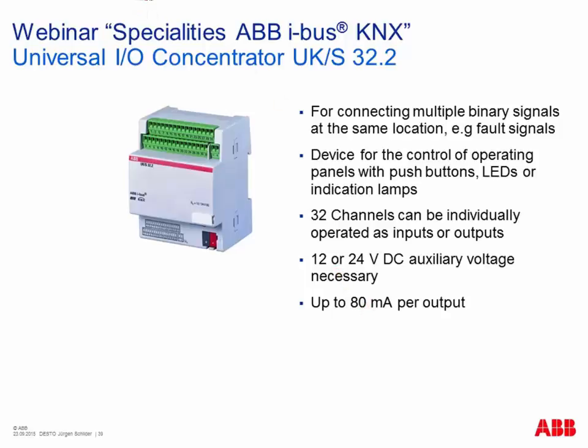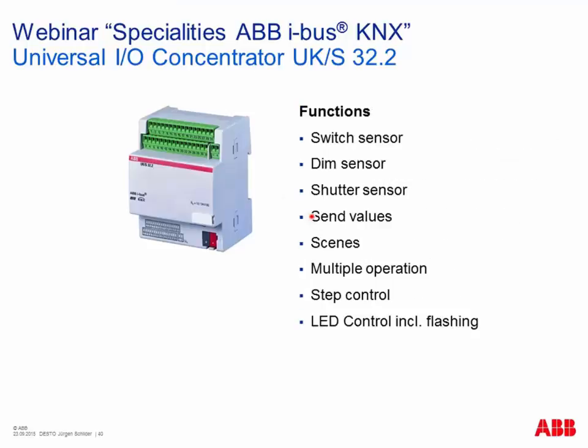And the input function mainly used is comparable with classical binary input, with all these functions from switching up to dimming, creating light scenes, and also multiple operation, which means by pressing many times you activate a certain power circuit, for example. Also flashing, if you connect an LED, for example, as an output, is available.